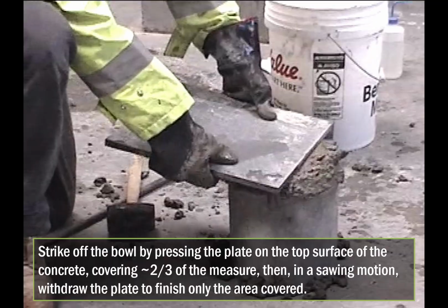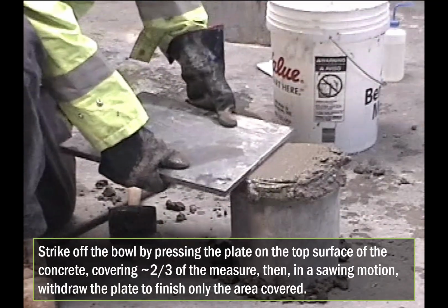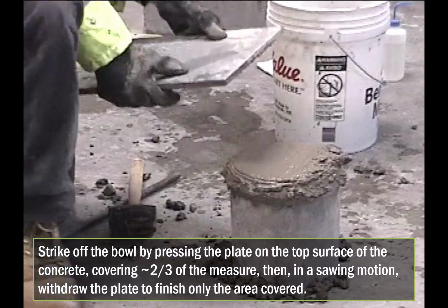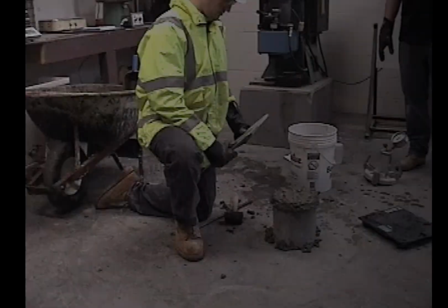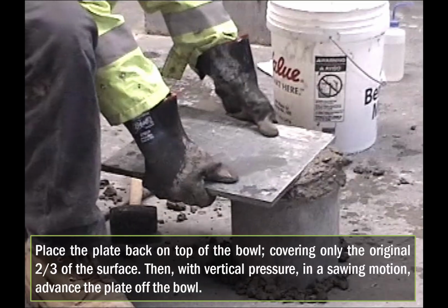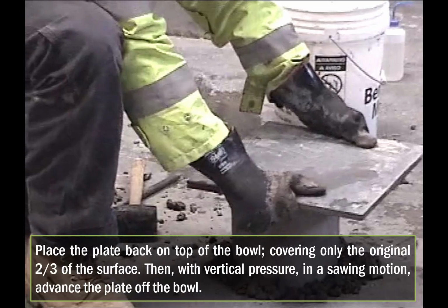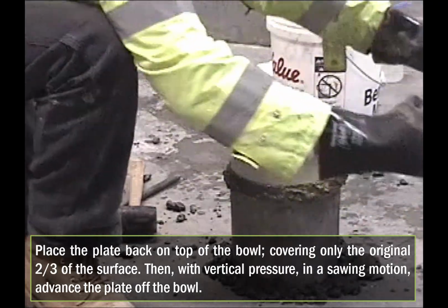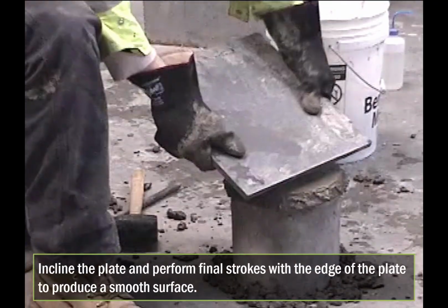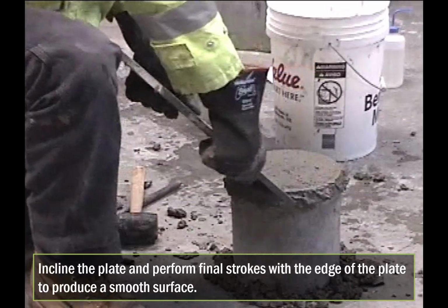Press the plate on the top surface of the concrete, covering approximately 2/3 of the bowl. Then, in a sawing motion, withdraw the plate to finish only the area that's been covered. Now, put the plate back on top of the bowl, covering only the original 2/3 of the surface. Then, with vertical pressure in a sawing motion, advance the plate off the bowl. Incline the plate and perform final strokes with the edge of the plate to produce a smooth surface.